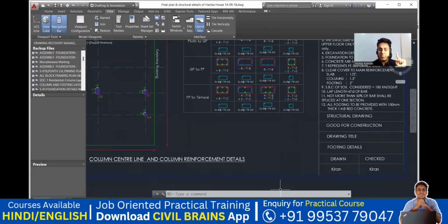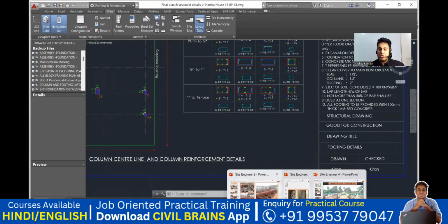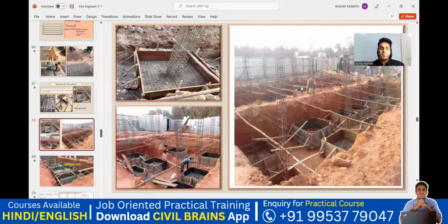And to put it in a better way, I can quickly show you one of the drawings for the columns. So this is how your column looks. Can you see a column here? This is that column. For example, if I say a 16 diameter 4 bar, this will be 1. This is 1. Then another bar we have, 2. Behind this we have another one, 3. Behind this we have another, 4. So let us say it's a 16 diameter 4 bar.